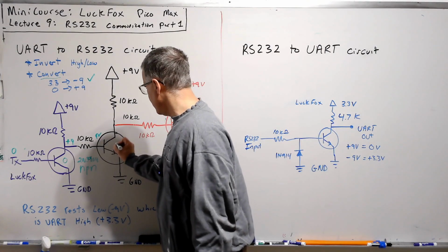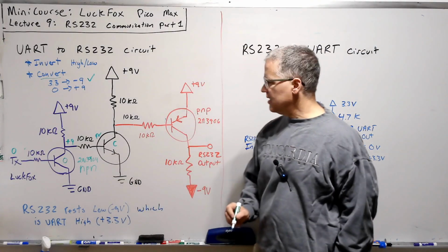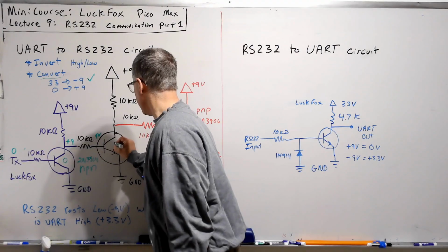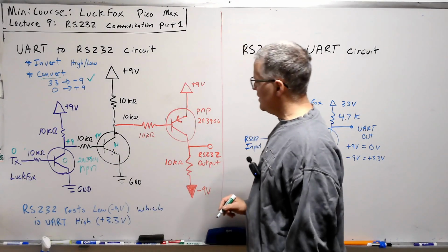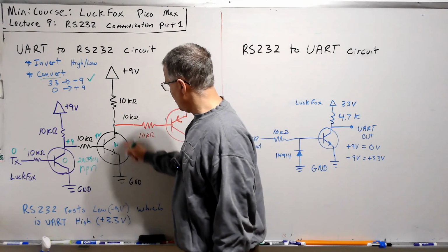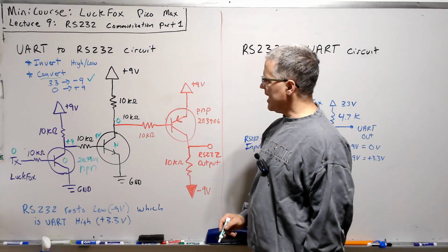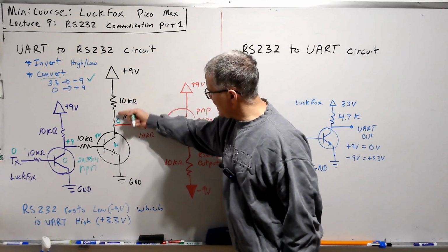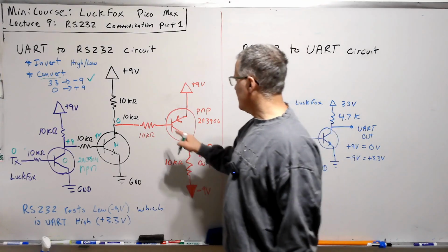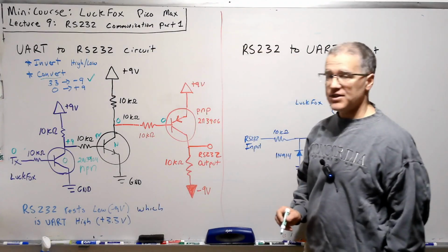And so this will be closed here. Or sorry, we were using W for wire. So this will act as if it's a wire, right, which will pull this side to ground. So we've got just now a 10K here, and this is connected to ground because that's acting like a wire. Well, if that's ground, if that's 0, that's 0.